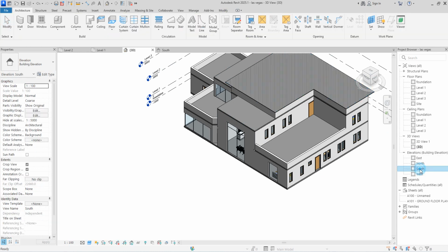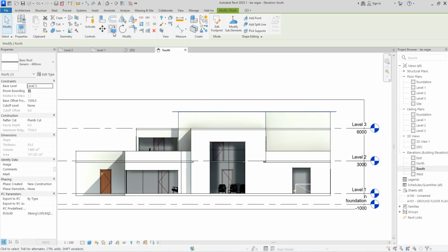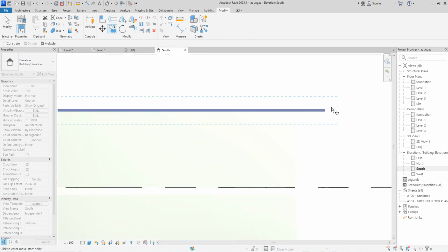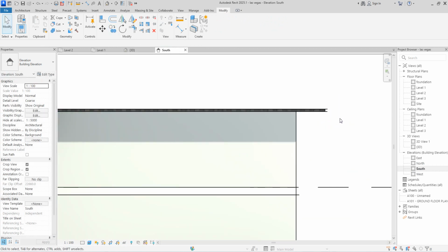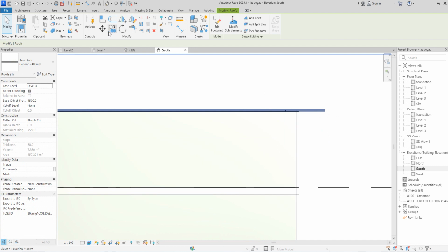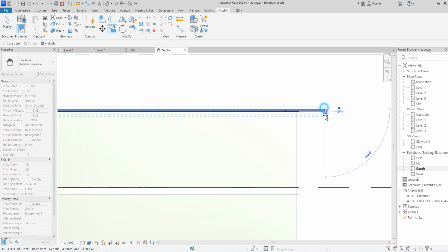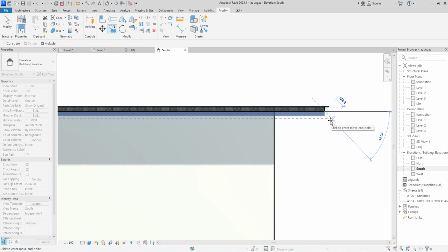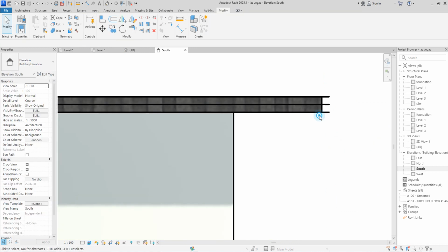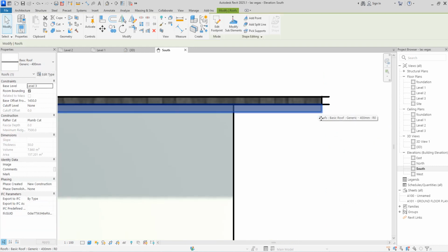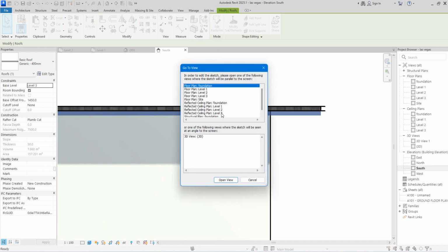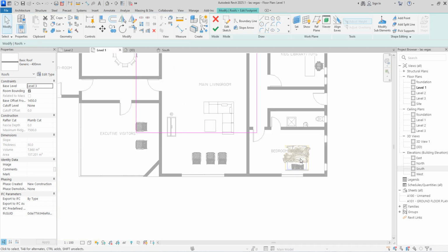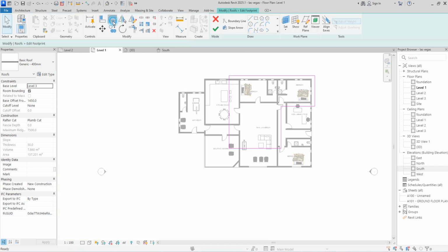So go to south elevation. At the south elevation, click on copy, then paste below. Clear, say copy, select this and paste something below it. Good. So the next thing you need to do is to edit it. Go to floor plan 1. Just like creating the floor plan, offset it without copy so that it will recess a little bit inside. So I'm going to give 75.